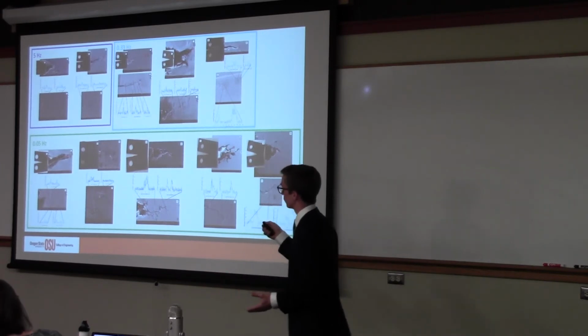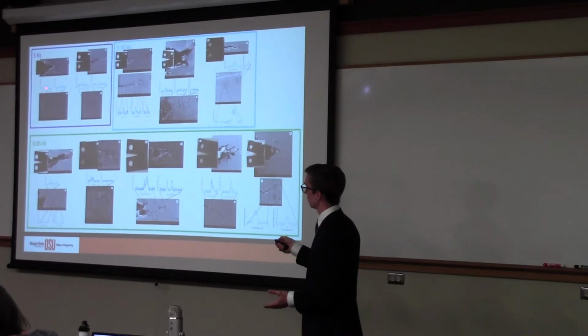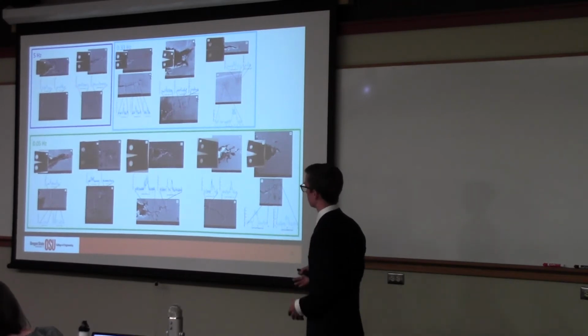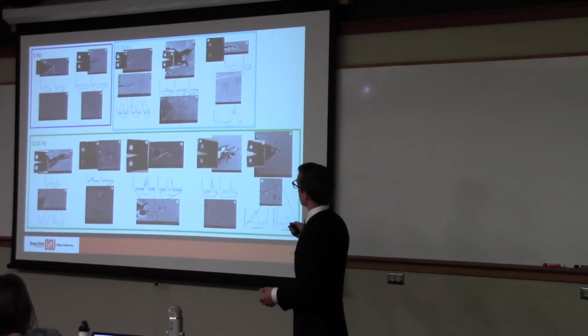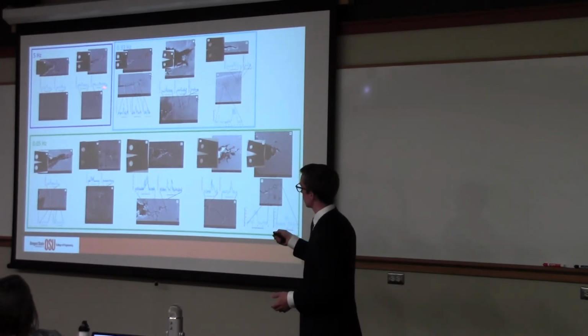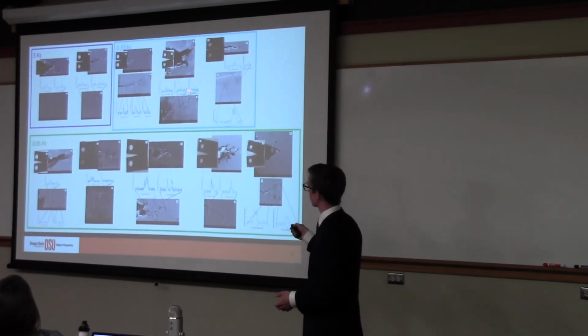We see that when there's less time for oxides to develop, we have lower little blue peaks of oxygen concentration. So this is oxygen concentration against line scan distance, since the plots are crammed in here to let you see them all. And so the 5 hertz, lower oxygen concentration, 0.33 hertz, a little bit larger, certainly gets larger as delta K goes up. This delta K is low, higher, highest, low, higher, highest.